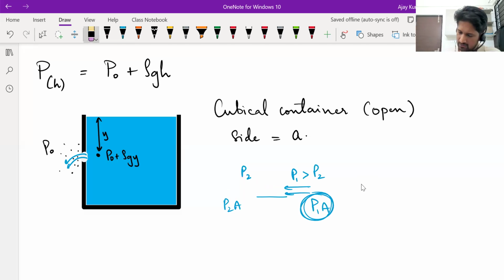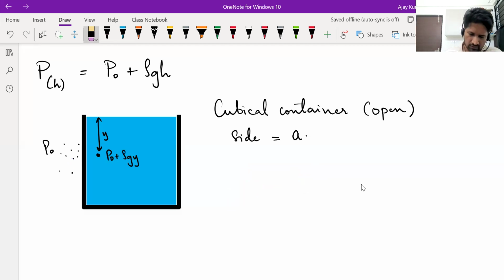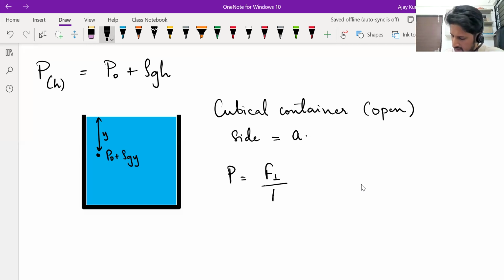So the same thing happens here also. If a hole is made, the liquid is going to flow out. Suppose the hole is not made, the liquid will still be exerting a force on the walls of the container, everywhere it is in contact with the container, and you can calculate that force also. By definition, pressure is perpendicular force per unit area. You can write it as dF by dA also, a small perpendicular force acting on a small area.